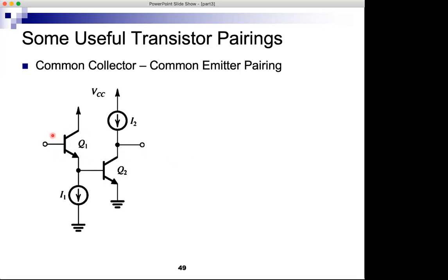What about other things like input resistance? What's the input resistance here? We will not show the small signal equivalent circuit, we'll just try to imagine that the input resistance here is the input resistance looking into the base. So R pi plus whatever is between the emitter and ground. So what do we have between emitter and ground?